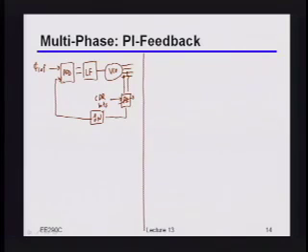So the idea here is actually very similar, right? Because now, instead of introducing that phase offset in the forward path of the loop, you're going to introduce the phase offset in the feedback path of the loop. The advantage of doing that is that, by doing this offset in the feedback, I just have to offset one of the phases that I'm using to feed back, and all of the rest of them will naturally track. Now, it also has the caveat that these CDR updates experience the PLL feedback transfer function. But since you typically want a low CDR bandwidth anyways, that's not too big of a deal.